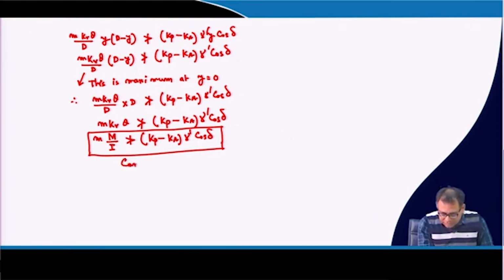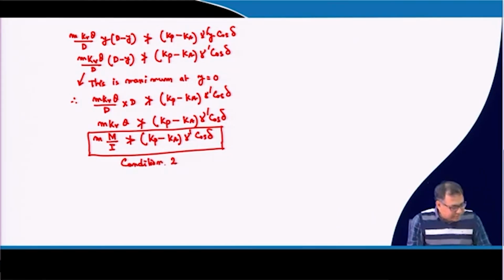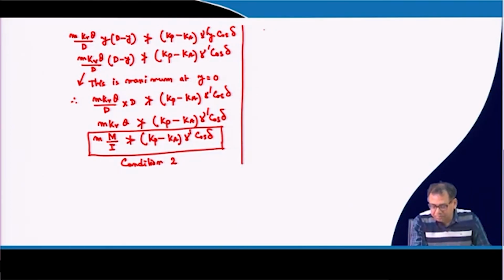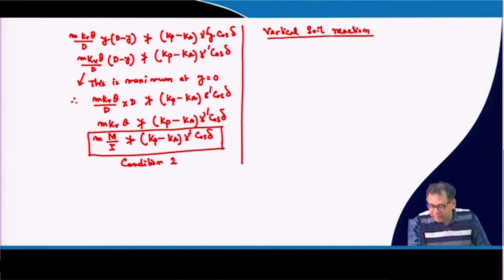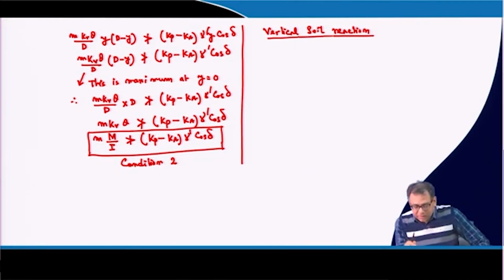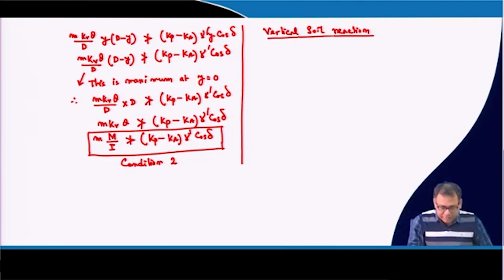So, next condition is vertical soil reaction. That means the stress which is developed at the base, we have to also check.